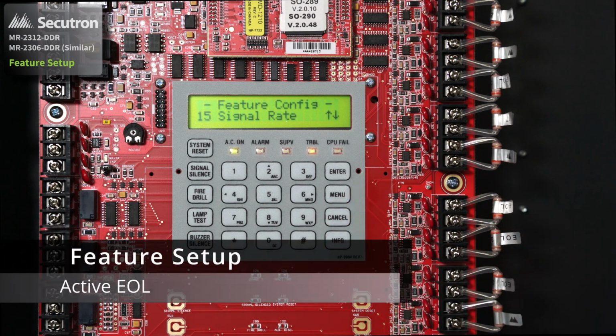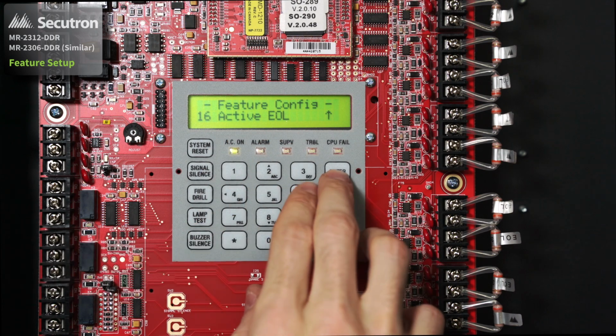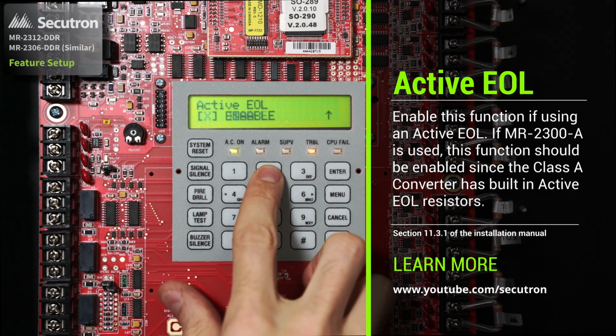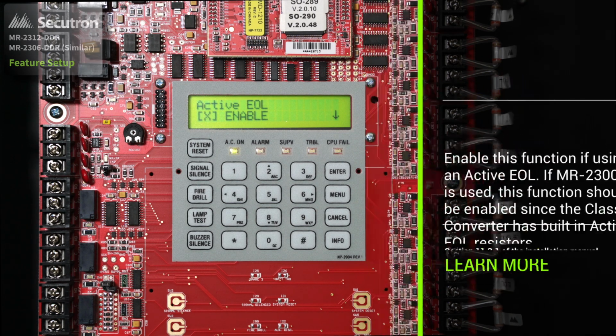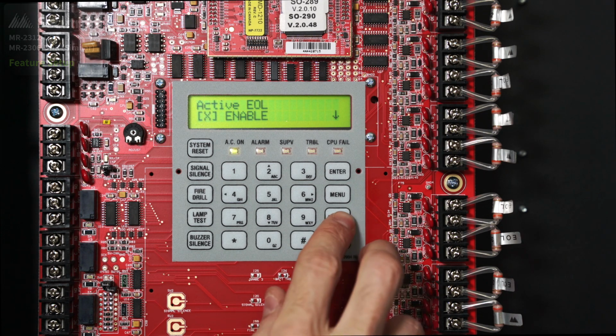The next feature is the active EOL. So by default, it has been set up as disabled, but if we'd like to enable it, we can hit the up cursor and apply the X to the enabled. Enable this feature if using an active end-of-line resistor. If the MR-2300-A is used, this function should be enabled since the Class A converter has built-in active EOL resistors.